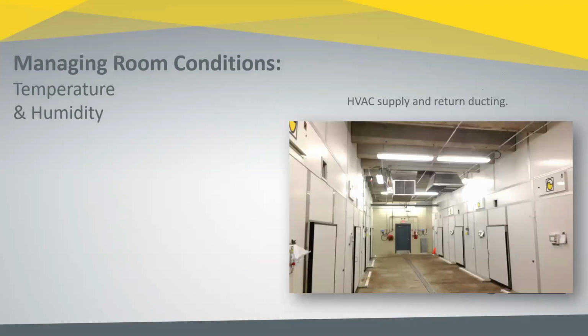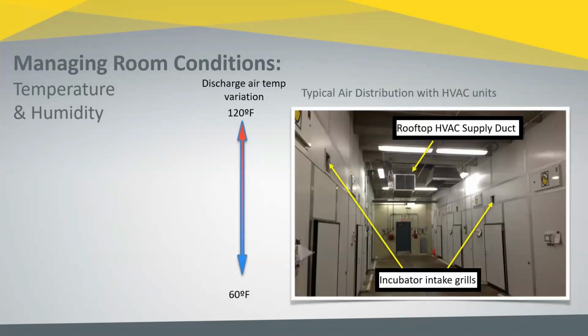When we look at a typical HVAC system, you recognize that your distribution points in the room are pretty minimal. Your supply air is essentially one duct that discharges air two different directions in the room, and you only have one return point. And with this, we can see a variation in air being supplied to machines. So machines that are very close to the return duct will see a more consistent temperature versus machines that are closer to the supply air discharge, and they'll see that big variation.